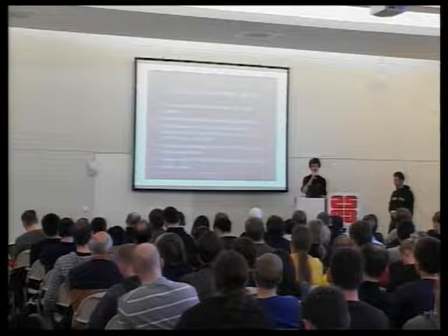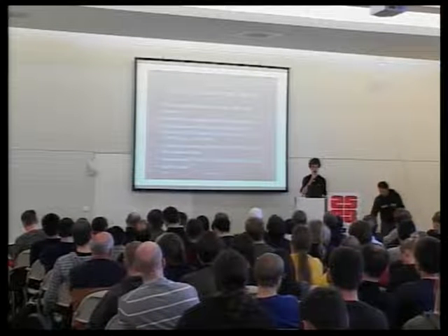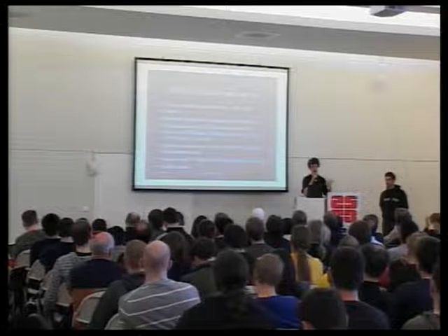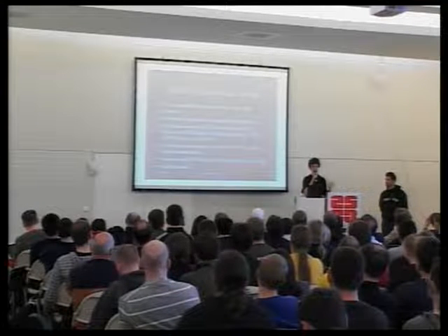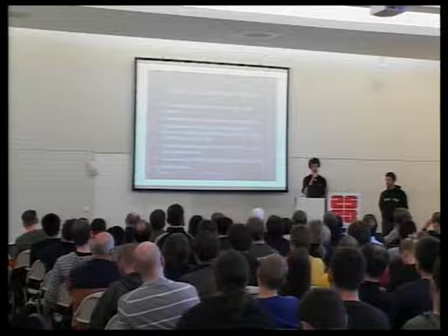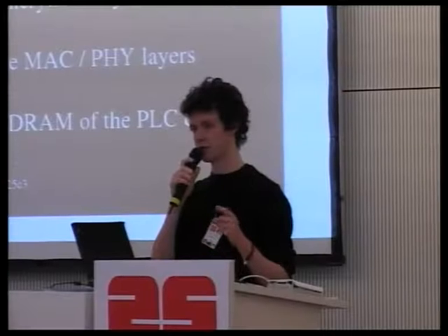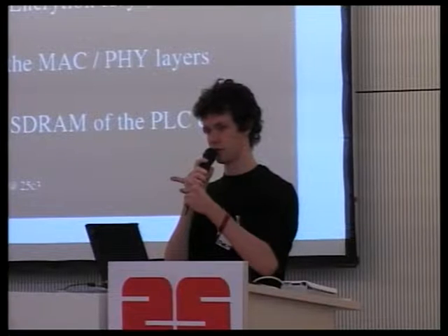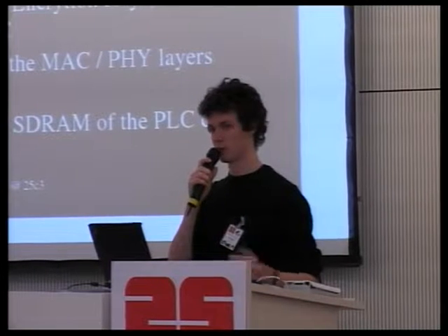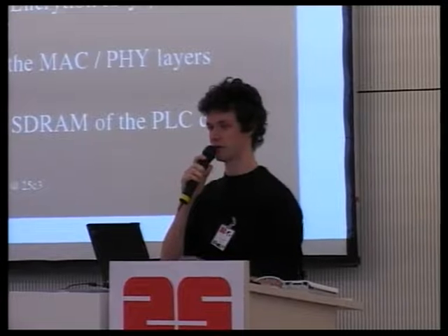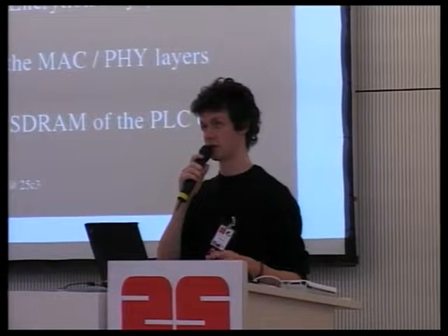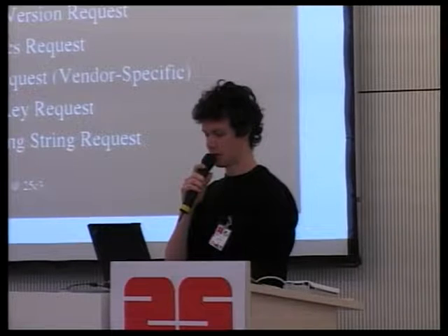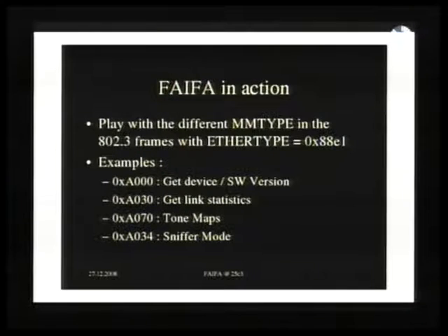And there's also something interesting in two senses. First one is the sniffer mode allows you to first see the beacons, which are sent by the stations, just like with Wi-Fi. And you can also configure the destination MAC address of where the sniffer should send Ethernet frames. So suppose you send this to a broadcast address, since it's sending something like 100 frames per second, it's kind of interesting. We'll make a presentation right now.